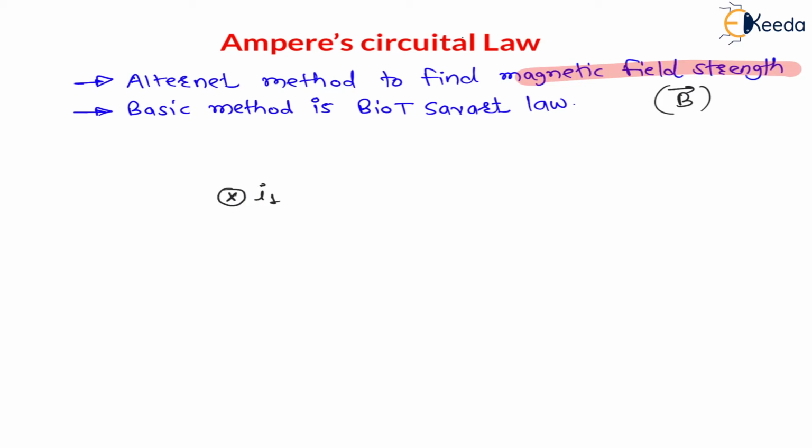And let us say one more current is I2, and this dot mark means the current is again perpendicular to the screen, but it is coming outside from the screen, right? And I1 is going inside the screen, which means the angle between I1 and I2 is 180 degrees, so from I1, I2 will get subtracted, right? This you have to understand.